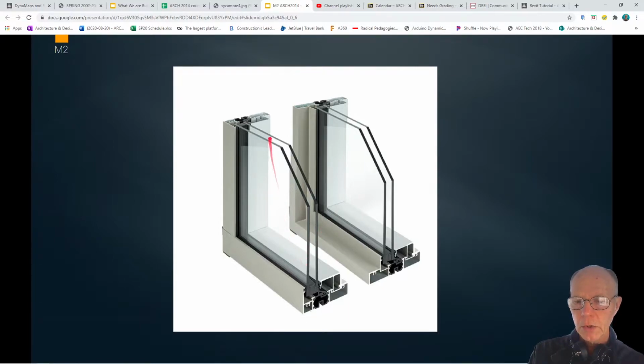So they're set into these aluminum, what are called aluminum extrusions. They're very complex in their shape. They allow you to snap them together. They all have fits to each other. In this case, there are pieces of rubber separating certain elements. That's intended to be what is called a thermal break. That means that this cold aluminum is interrupted by a plastic or polymer that doesn't allow heat to transfer in.